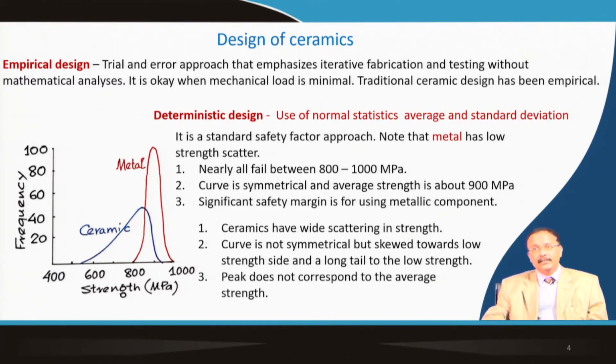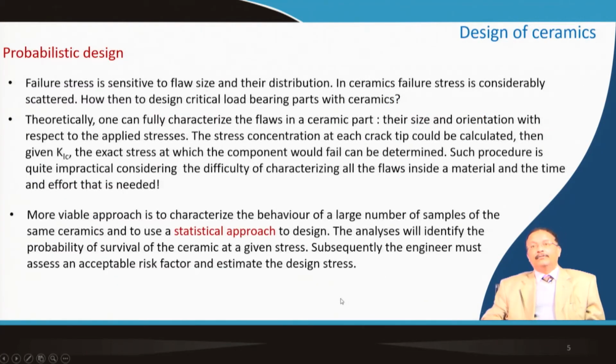This deterministic approach to design, just by going for the average or the standard deviation, which is the strength minus average, squared, divided by the number of occurrences, simply does not work for the ceramic article. So, for this kind of thing some kind of probabilistic design is required.